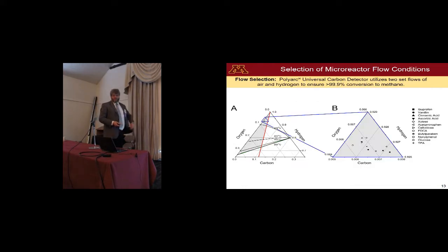You can do this with an approach that's similar to catalytic reforming, and you can get insight from that. If you think of any of these catalytic systems, you have some distribution of carbon, hydrogen, and oxygen, and you can think about what conditions are very strong for methanation. So if you haven't seen one of these ternary plots before, you can just think of it this way. If all the compounds go into a single pot, I can add up how much carbon, hydrogen, and oxygen they are, and place those molecules somewhere in this 3-parameter space.